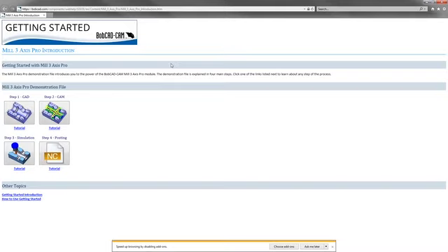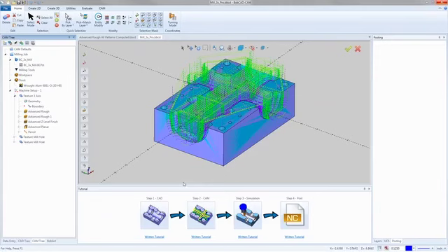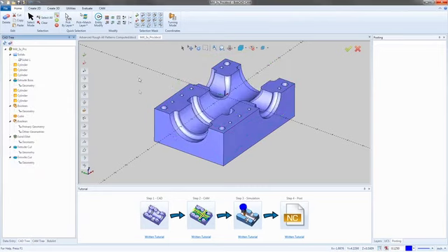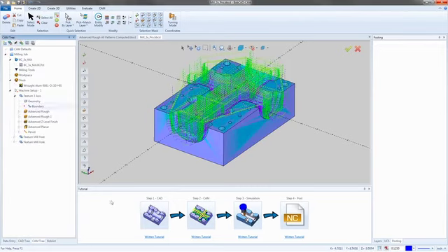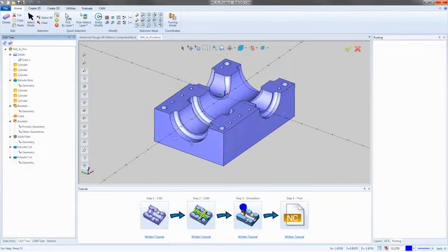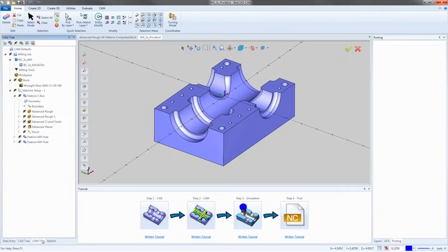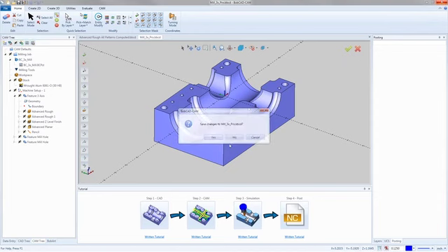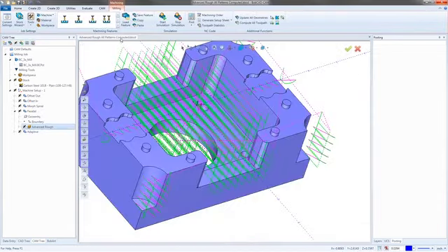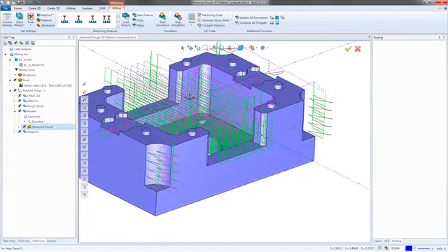You'll get a written tutorial for every one of those, as well as down at the bottom, you have CAD, CAM, simulation, posting. The buttons actually do certain things too. So if I click CAD, it hides all the toolpath, lets me see the CAD tree. For a part like this, where it's got these long open-ended portions, that's a really nice one for that parallel style pattern. But if it's a part like mine where it's closed off, I'd prefer not to use that toolpath, but it just depends on what you can get away with.